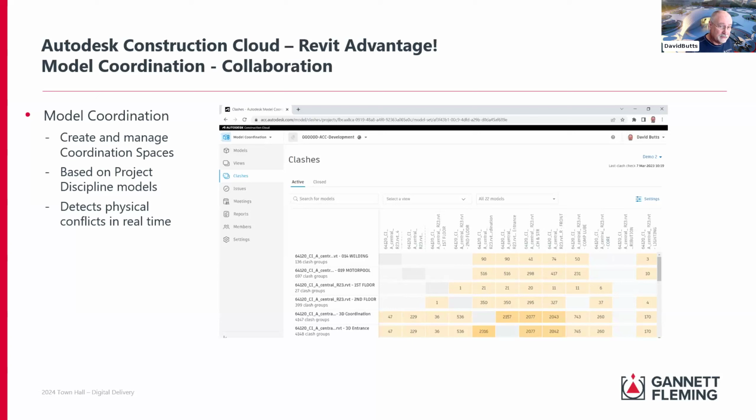Then we started using Navisworks. If you're not familiar with it, it's Navisworks Manage. It's been around for decades. It's a kind of agnostic file format where you can bring in everything. You can bring in Autodesk, Bentley, AutoCAD, it doesn't matter. You can bring all these files together and mash them up into one model and actually see conflicts, and do soft and hard clashes. So you're not just physically touching each other, but a clearance around an object. You can use Navisworks for that.